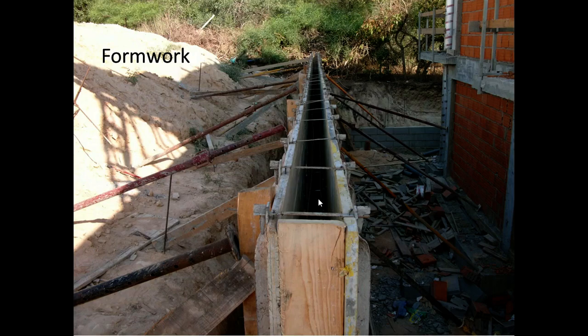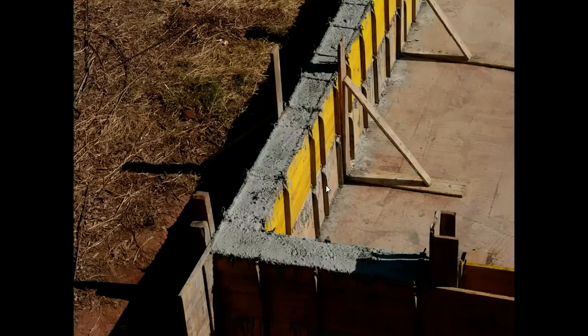But you will notice in here that there's some little steel rods. Now it's actually a cage of steel. That's the reinforcing. That's the steel reinforcing for the concrete, which is placed in first. Now it's tied together, of course, but when you pour the massive concrete in here, the weight of it is going to be pushing on this very simple timber shuttering. It will be pushing on them, so we have to tie it together to stop that timber shuttering failing, don't we? There it is once it's been poured.